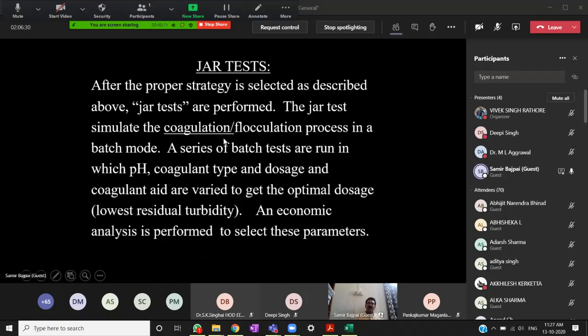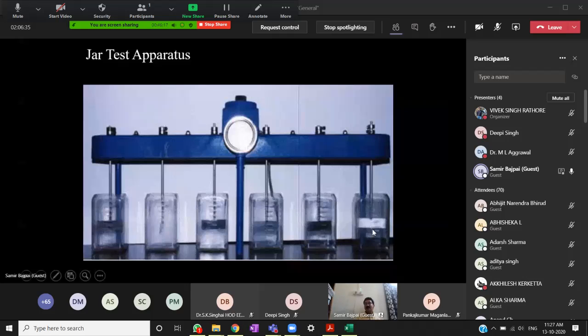How much coagulant needs to be added is determined through a jar test, where we take a series of jars in which we have our water sample. These are typical 1 liter cylinders, and these are stirrers having paddles, rotated by a motor installed on the top. We have a blank where the original water sample is there. In the other samples we add different coagulant doses, initially mix the coagulant in rapidly, then slow mix it for say half an hour, and then see which results in the best settling by measuring turbidity.